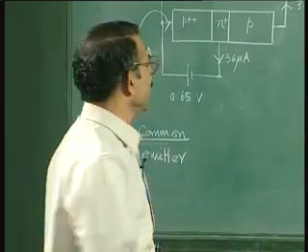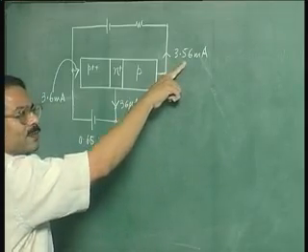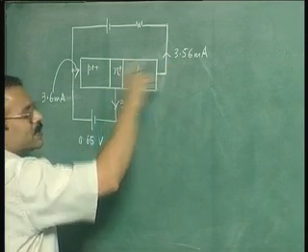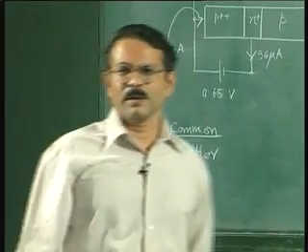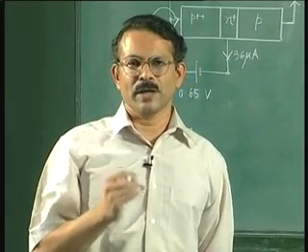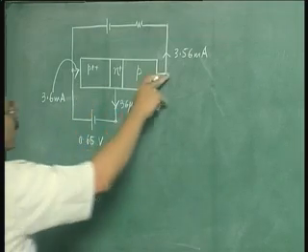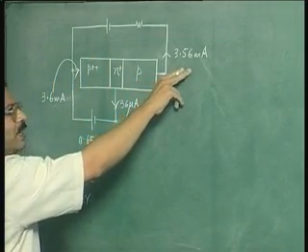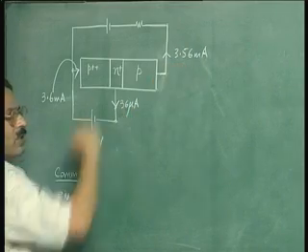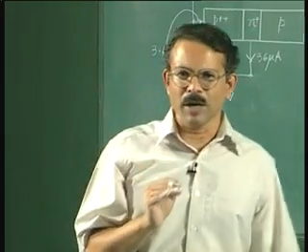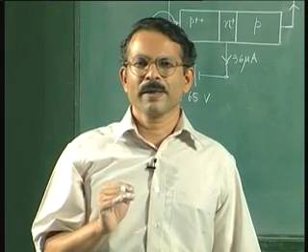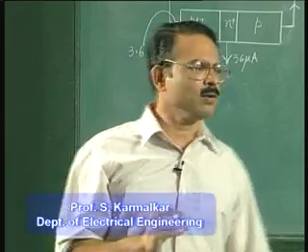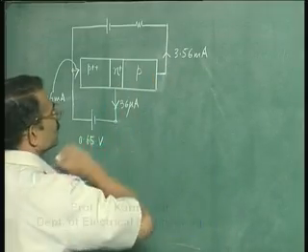Okay. Should we not add IC naught here, because this we have calculated for zero bias condition? Yes, when the collector base junction is reverse biased, we must add the current because of IC naught. In fact, the current that you will have to add in the common emitter configuration will be slightly different from the current you need to add in the common base configuration. But since IC naught is small, we have neglected it. We will justify this approximation later on. So right now let us not get into the effect of IC naught.